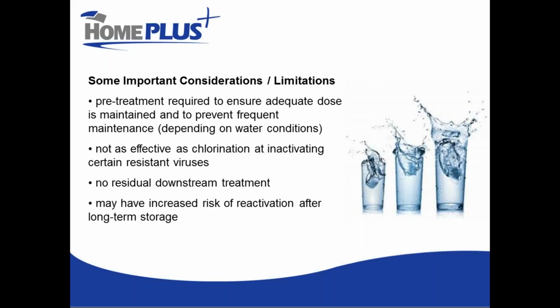The frequency of that will be determined largely by the water conditions, but it's not something that we can neglect and expect to have it keep operating efficiently and effectively for us. As I mentioned, there is some resistance of UV disinfection from certain resistant viruses, so it's not that effective at inactivating certain viruses, unlike chlorination.